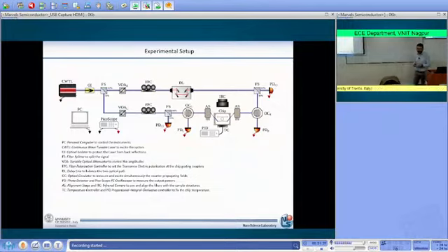An optical circulator is a device that has 3 ports: the light from port 1 is transmitted to port 2, the light from port 2 is transmitted to port 3, and no light from port 2 goes to port 1, and the light from port 3 is transmitted to port 1. Therefore, the input signal is inserted into port 1, and it is transmitted to port 2.